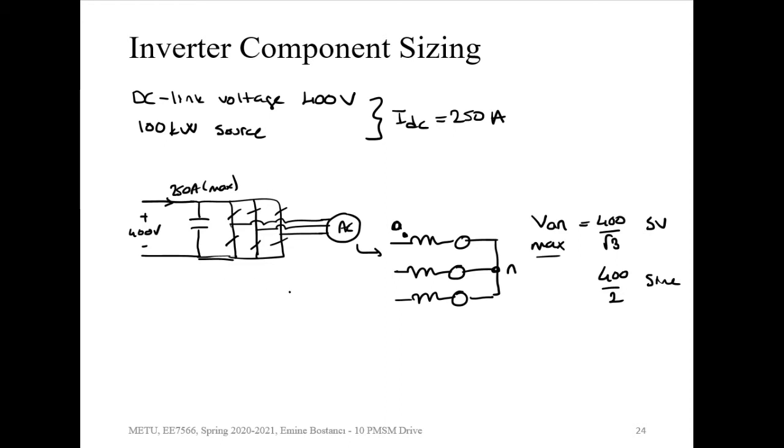But in this case, we need to consider the characteristics of the load. These are the induced voltage characteristics of the load. For example, if we have an AC machine, we talk about the power factor. AC machines usually operate with a lagging power factor if you don't control them to work in a different operation mode. Permanent magnet machines can operate with high power factors, so it can be 0.9 to 1 or maybe 0.8, depending on the operation.